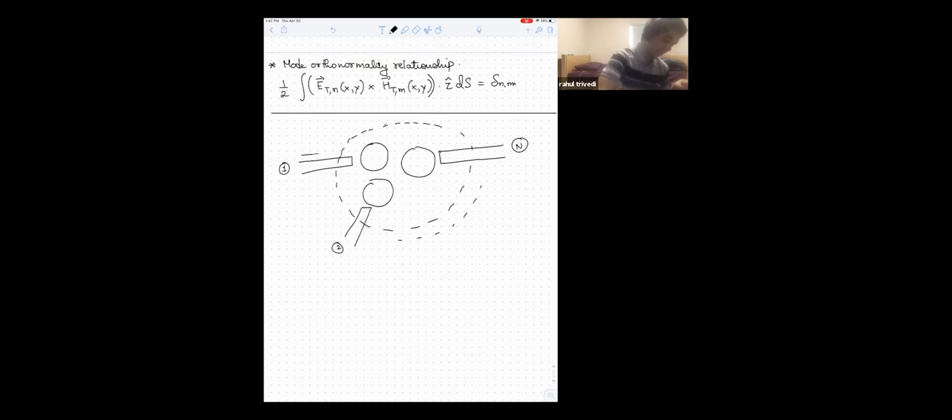So you can imagine each waveguide can give you an input into the cavity region, which is injecting a propagating mode into the waveguide. And then based on however the cavities interact with the waveguides and interact with themselves, there is some backward propagating mode that's coming out of the waveguide as its output, right? So we have some input signal B1 plus as a function of frequency, and you have an output signal B1 minus as a function of frequency, right? For each waveguide, and so on, right?